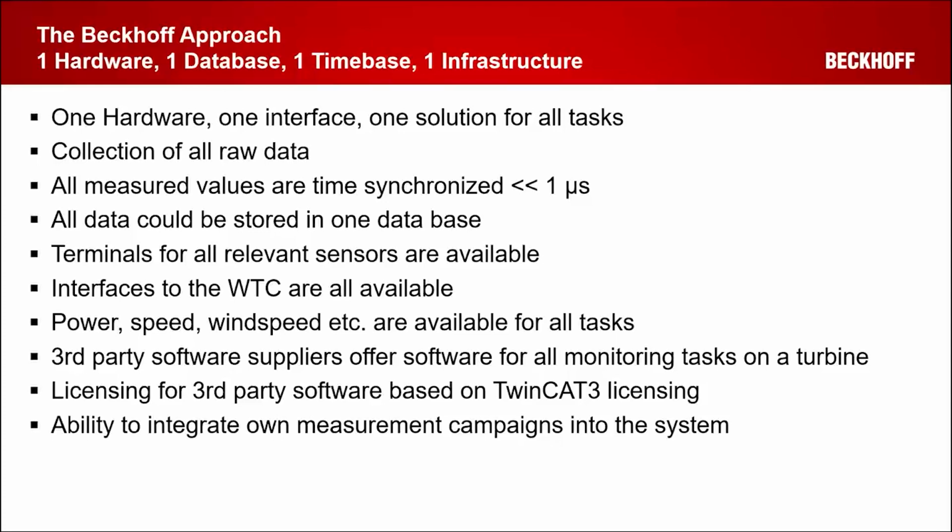And that means also all the data is already there, like the wind speed or the power or the drivetrain rotation. The main control system already knows that, and inside the software, combining these TwinCAT modules is just an easy configuration and a mapping between the data signals and the data values. So the third-party partners, as we see later, now offer software for this to implement their specific knowledge of mechanics or vibrations into a software module and integrate this into the TwinCAT platform.